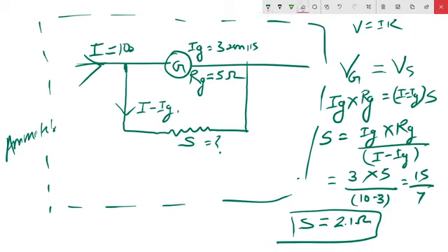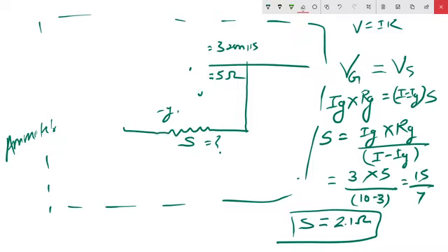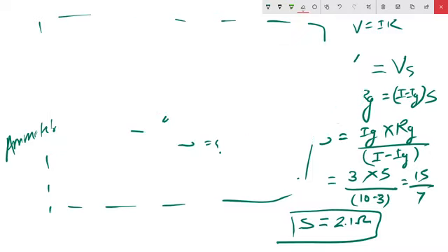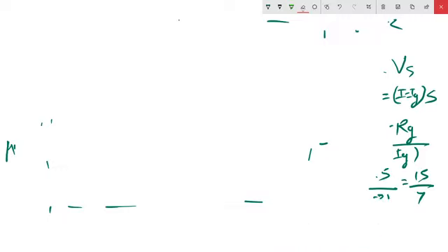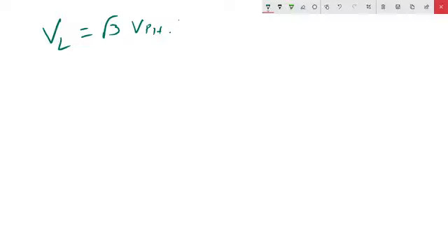So the next question, if you see, they're asking: in a three-phase star connection, the phase voltage is measured at 440 volts. What will be the value of the line voltage? As we know, this is theoretical, and proven also as per the circuit diagram. If you want that, it's available on YouTube also, and if you want, I will make a video separately on this. But you should always remember, in the case of a star connection, VL is equal to root 3 times V phase. So here VL is equal to root 3 times 440 volts. This will be your correct answer.